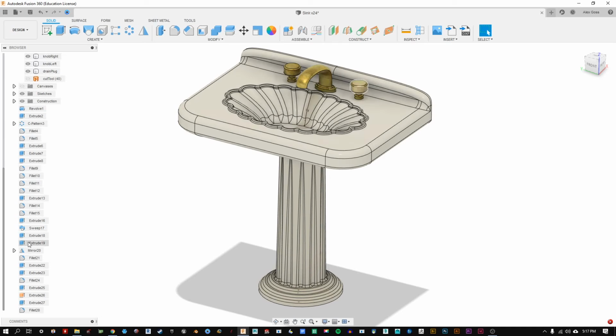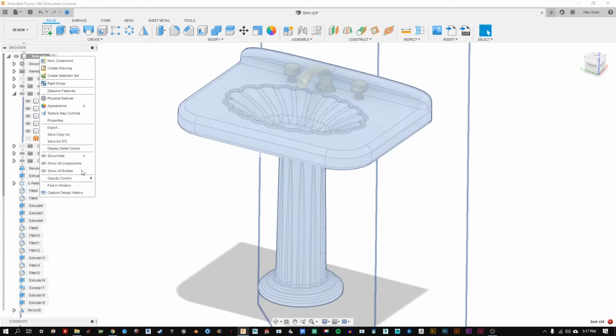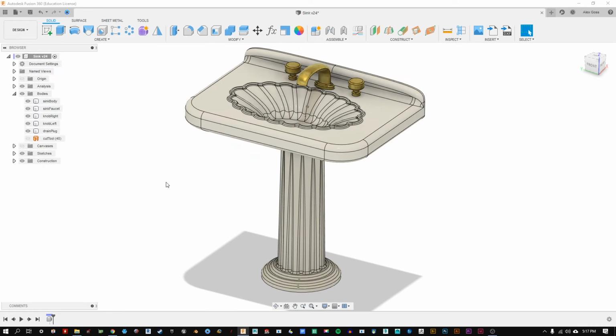We can talk more about the benefits as we go through, but I'm going to talk mostly about designing with history, because this parametric way of modeling, meaning based on parameters, is really powerful if you want to change things or have things relate to one another. The intent to use parametric modeling gives us those options later down the road. So whenever I can, I like to capture history. Now, if I went from something without history to history, do I retain that history? No, I don't. Nothing on my history timeline is there anymore, so I've lost it.